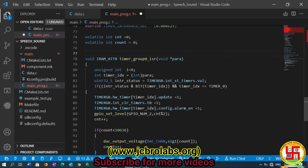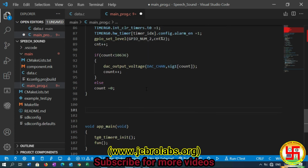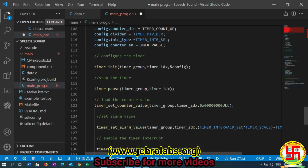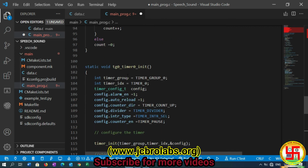Now here, if you have any difficulty understanding the timer, you can visit our previous video. I just copy that code here. This is our tg0 timer 0 init function, timer group 0 and timer 0, and config is a structure type, with alarm enable, reload 1, timer count up, divider, and timer interrupt select.